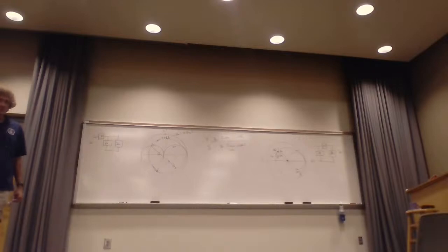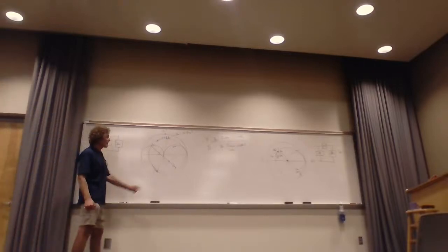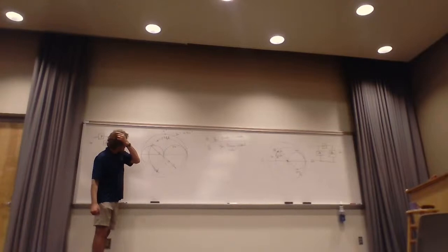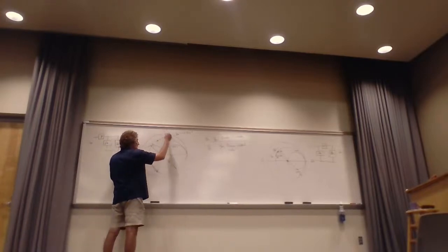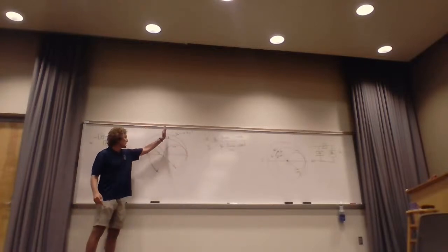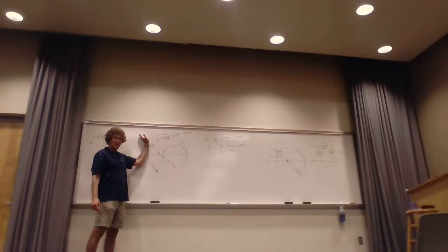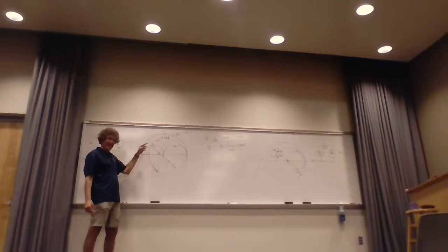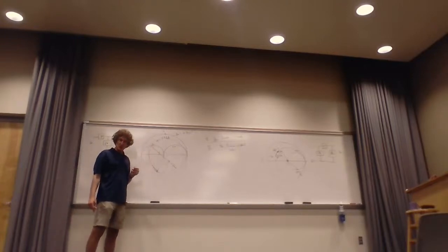Do y'all follow me? So based on that, if I came in here and I wanted to add admittance to get to here, remember, actually, I should show you this. This is the way the admittance values look. That's j1, j0.5, and so forth, on the outer edge. So here, if I have 0.3 plus j1, I would want that j value to be reduced to hit this. So I'd be adding a minus j something. That would be a capacitor, wouldn't it?